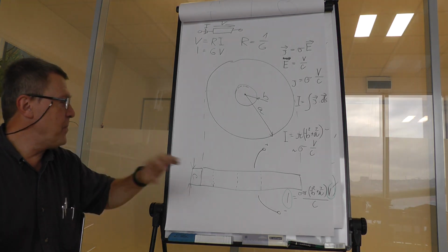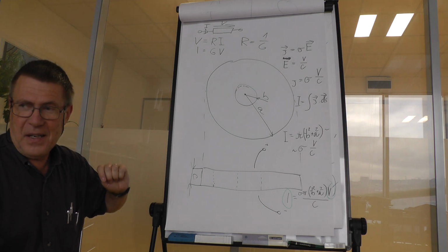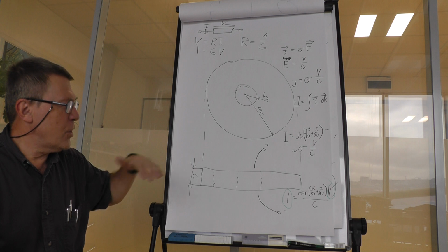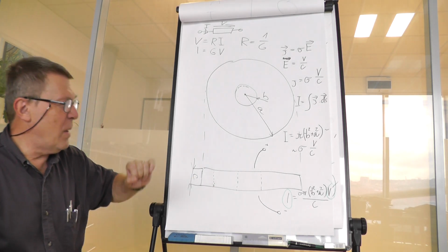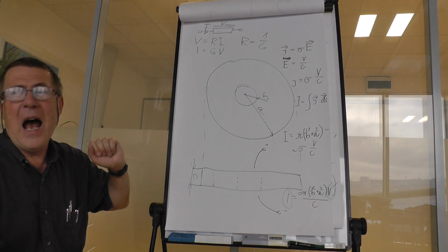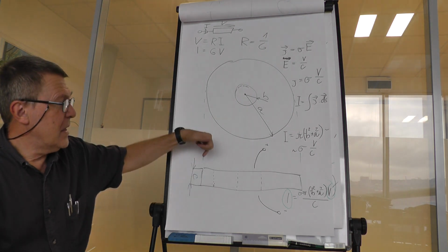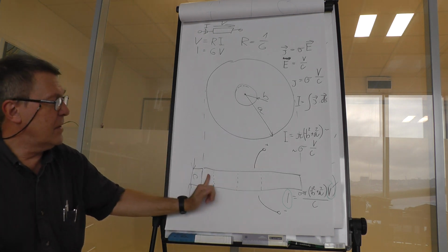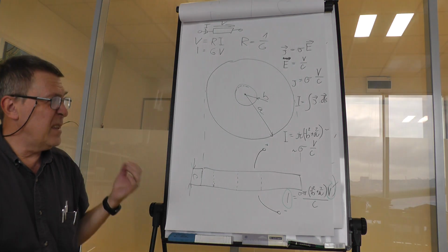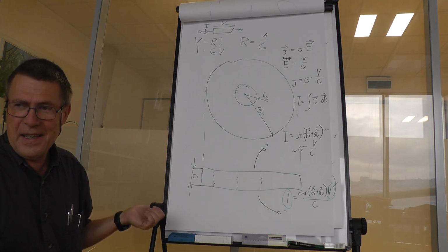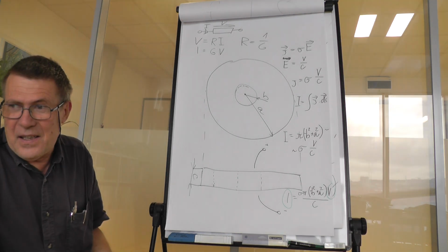So now please, the important points. We have established a resistor in a manner that geometrically creates a homogeneous steady current field inside it. So at any point we have the same field strength E and flux density, that is current density, J. The direction does not change, neither the density nor the strength changes. So this is called a homogeneous field. And within this field, we can easily get the value of the integral value, that is current here, by multiplying current density and cross-section.